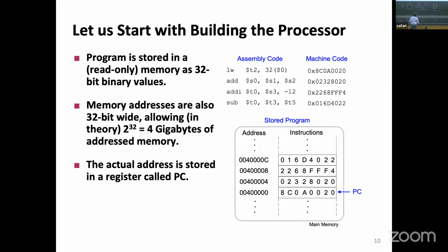Now, again, one of my favorite guys. Oh, my God, I forgot this multiplexer. Now here I have 2 options. Once again, a multiplexer comes into play. The value that goes as the second part of the ALU either comes from the constant, the immediate, which was 16 bits, gets extended to 32, so that I have a 32-bit value. If this is 1, I pick one of them. If it is 0, it's an R-type operation. So this is the source A, this is the source B in the book.